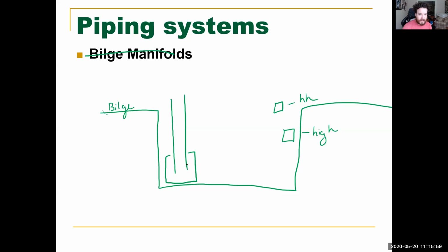So basically what you have here, this is your bilge well. And that's where naturally everything's going to flow, it's almost like a road where roads are pushing water to the side so that it goes into the drainage system. This is going to be pushing water and flowing all the liquid, all the oils, everything that drops into the bilge. It's all going to flow into a bilge well. So this is where you're going to suck from.